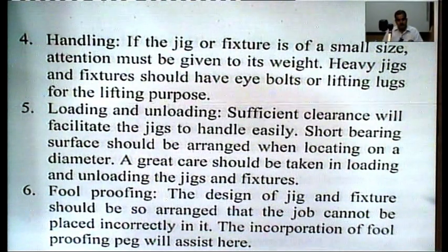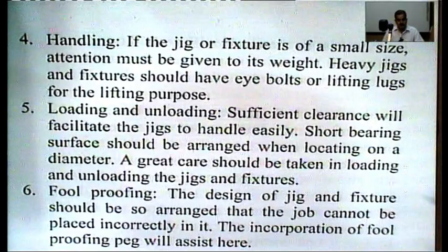If there is very small clearance, then loading and unloading will be somewhat difficult. So sufficient clearance will facilitate the jigs to be handled easily. Short bearing surfaces should be arranged when locating on a diameter. Great care should be taken in loading and unloading the jigs and fixtures.